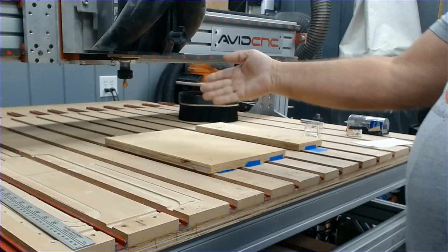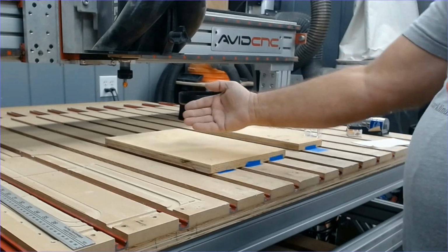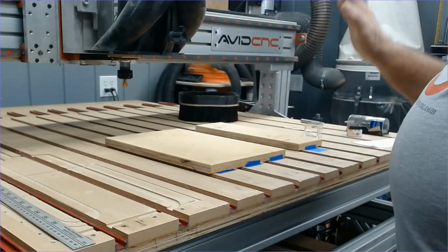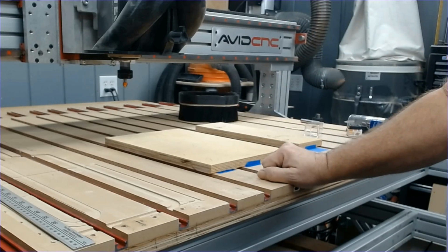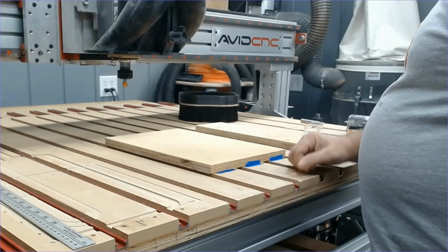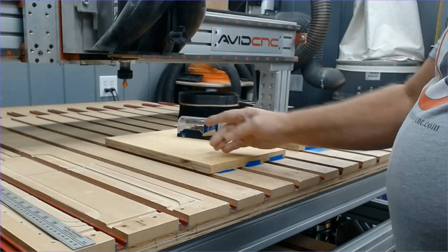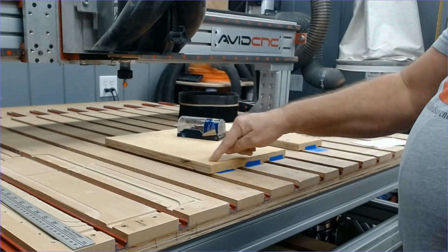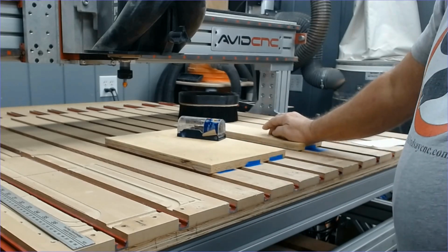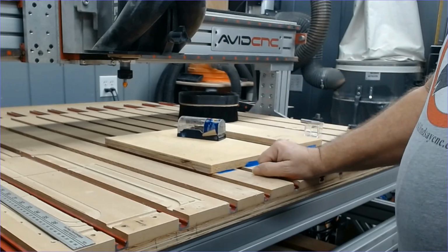And the way I'll do that is, once the toolpath is finished running and the machine has come back to the home position, the spindle shuts down, I can then take my wrenches, take out the bit, put my new bit in the spindle, bring it back over to my Z0 point, be it somewhere here or over on this material, and set the Z0 for that bit.